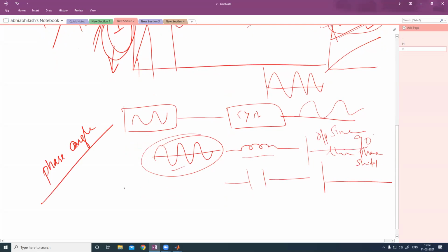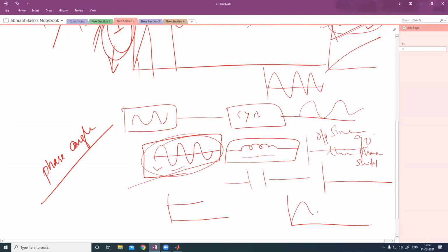And this is the only signal that a linear system will retain like that. If you give a step signal like this, the output will be something like this. It will not follow the step at these points. But with the sine wave property, the output will also be a sine wave, with a phase shift.